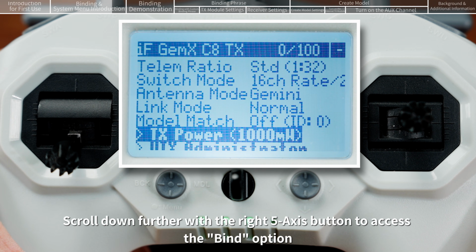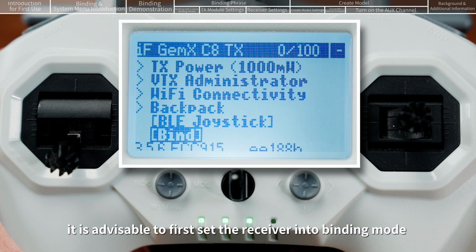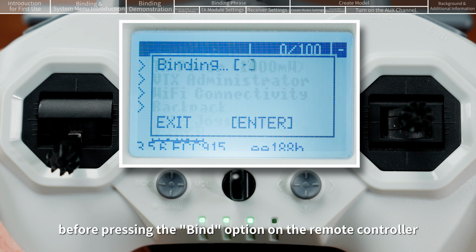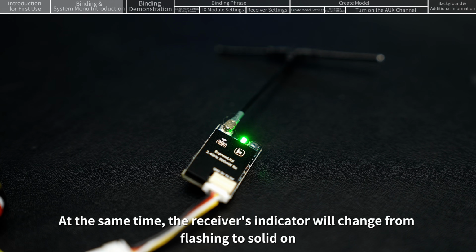Scroll down further with the right 5-axis button to access the bind option. Due to the time-limited binding window of the transmitter, it is advisable to first set the receiver into binding mode before pressing the bind option on the remote controller. After a successful bind, return to the main interface to view the signal strength indicators. At the same time, the receiver's indicator will change from flashing to solid on.